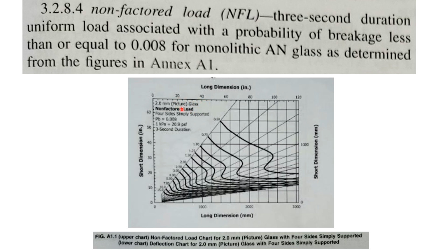This is your non-factored load. That's what we're looking for here. This is your 4 sides. Now, this is a 4-side simply supported glass. You've got to make sure if you're doing these, you use the right glass. And here's your 0.008 again. This is your probability of breakage.